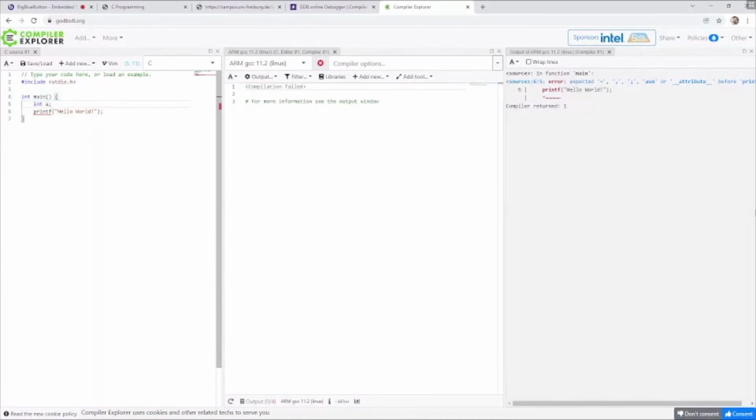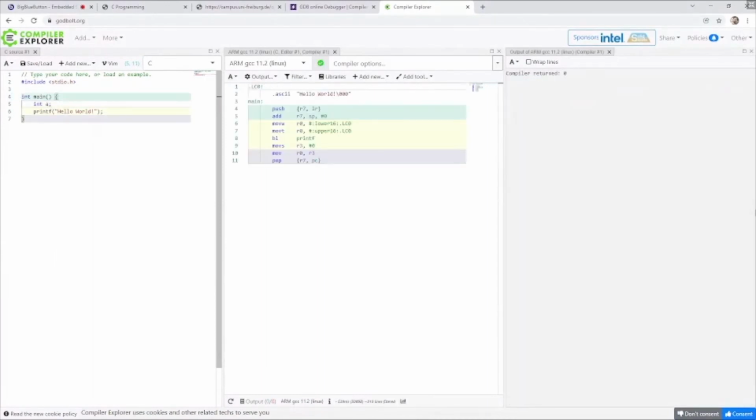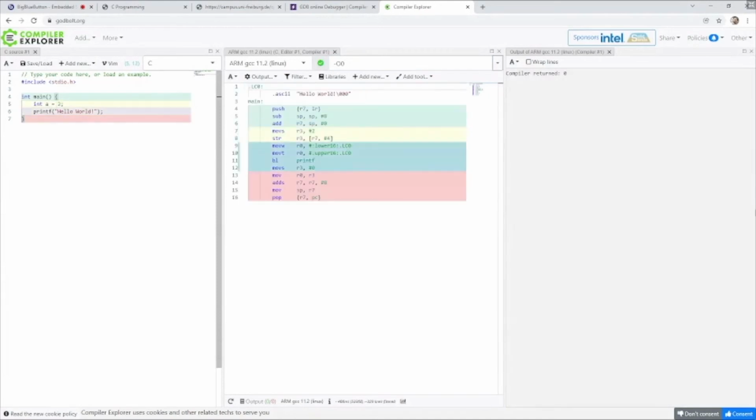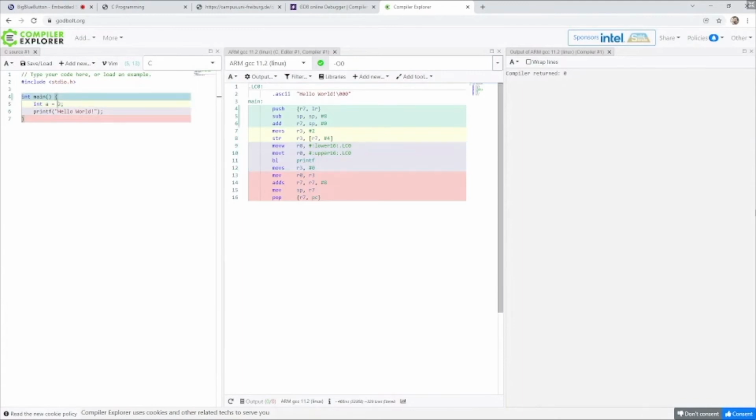local variable in here. If the optimization is turned off, which can do like this, optimization, then you see that the stack pointer should have changed. And yeah, you see, I think this one is then the stack pointer modification to allocate a variable for E2.